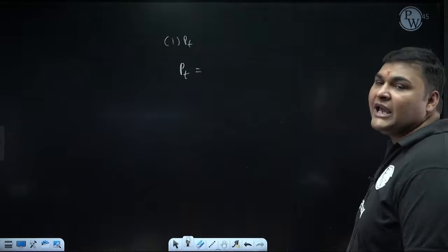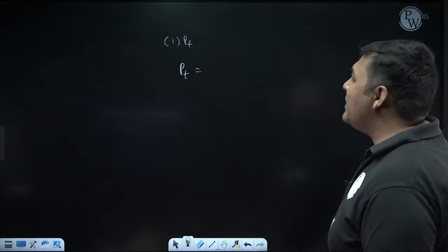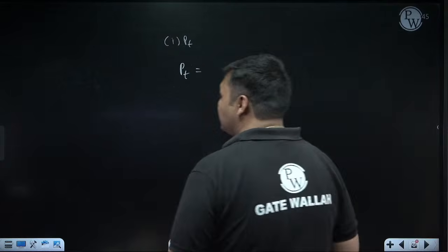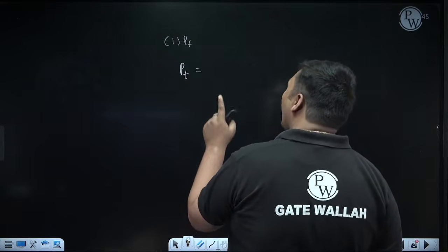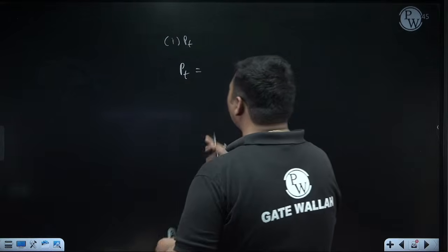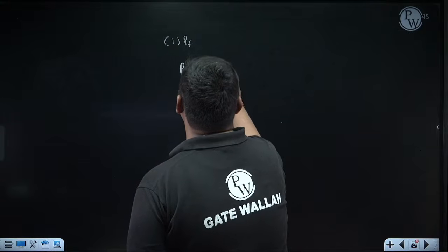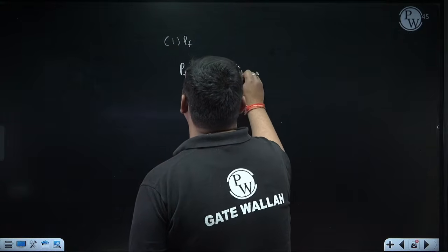Load capacity to avoid tearing failure. In tearing failure, tensile failure occurs. Since we are calculating tearing load carrying capacity, it is not the actual load. The actual load should be less than or equal to this to avoid a tearing failure. So to calculate this capacity, we will equate actual tensile stress with permissible, that is sigma TP,